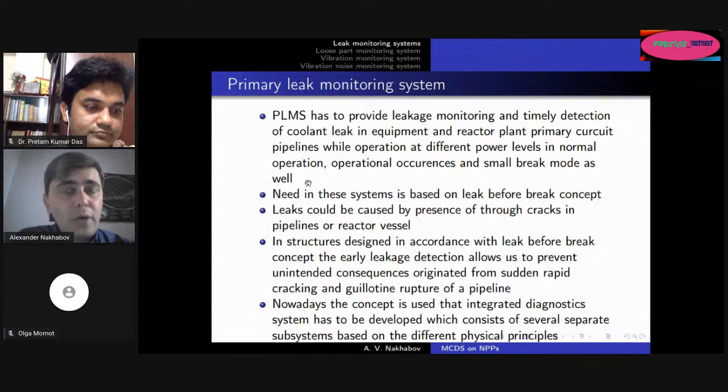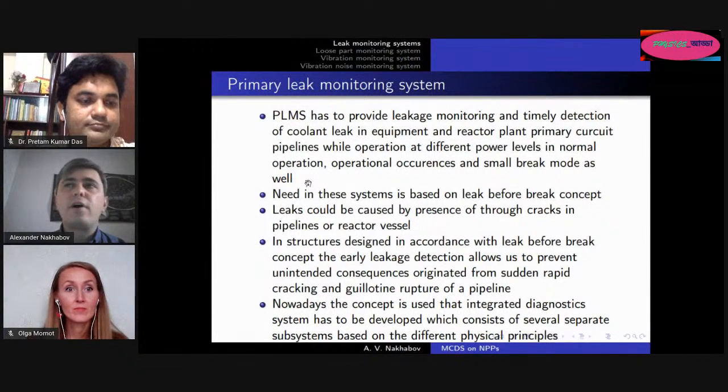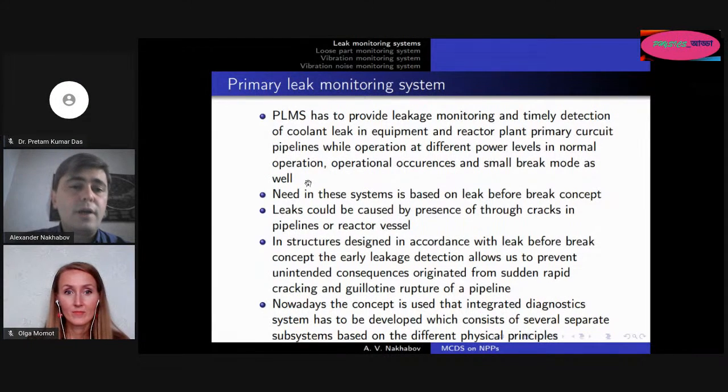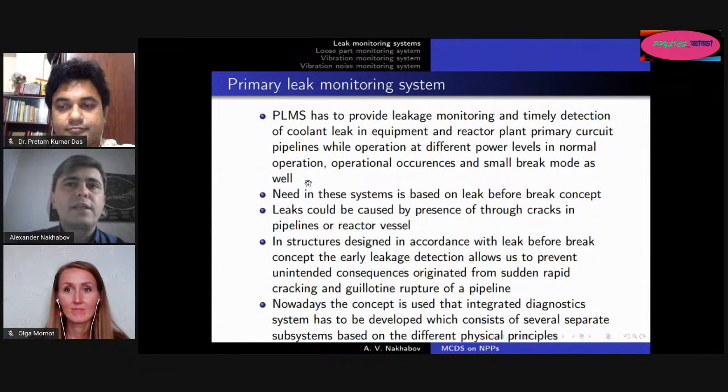But if the operator really finds a difference of 2 megapascals, from 17 down to 15, it will mean we have a huge leakage, because a 2 megapascal difference means there is a huge leakage from the primary circuit, and of course it's too late to talk about prevention. In this situation, we should declare an accident, and we should provide special actions to cope with the accident itself.